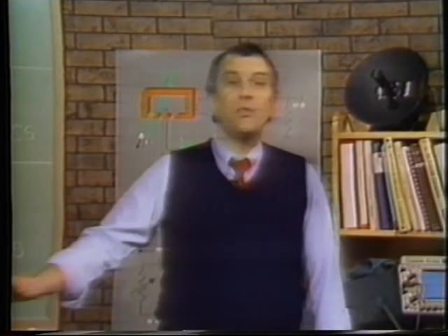When that isn't possible, active probes are the best solution. They offer high resistance and low capacitance to the circuit under test. Proper ground lead use is crucial to most voltage probe applications. And finally, some measurements can be effectively performed only by current probes. Hopefully, I've introduced a few concepts that will improve your measurement techniques. Probe selection and use are neglected topics, and many important considerations are anything but obvious.